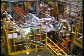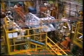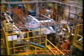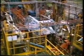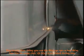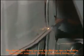Spot welding, with the electrodes maneuvered by articulated arm robots, is commonly used to join sheet components of automobiles. In seam welding, coordinated pulses of electric current from rotating wheel electrodes produce a series of overlapping spot welds, resulting in a leak-tight welded joint.